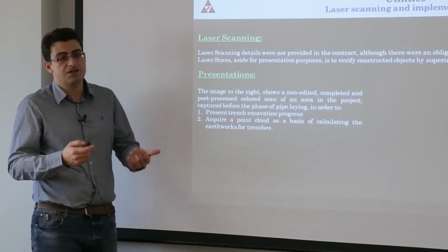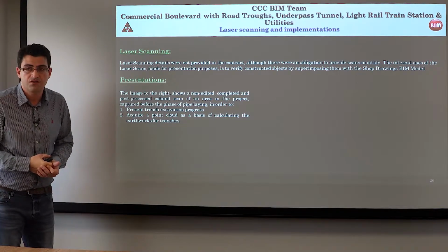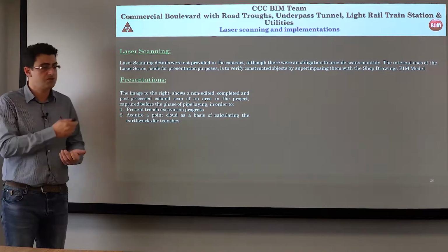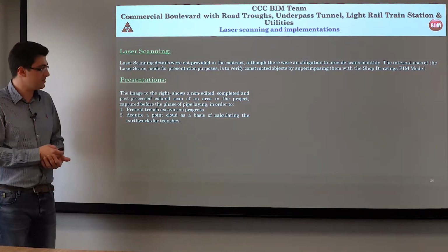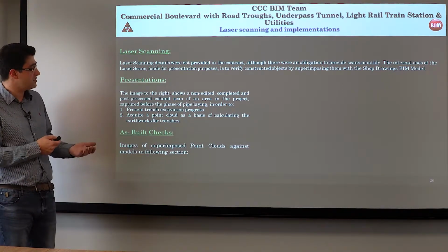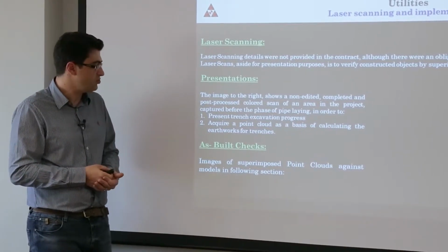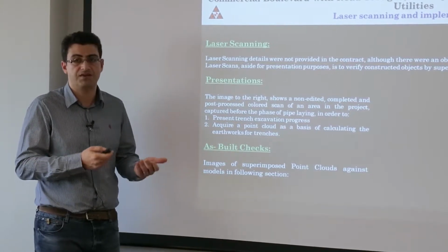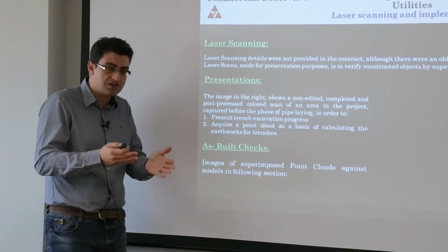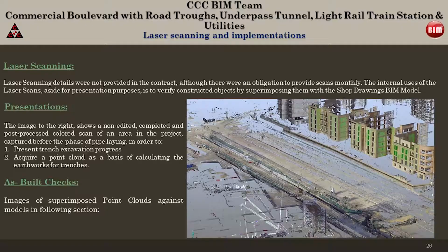And as we found out in our project, we could utilize the point clouds for the excavation, earthworks and backfilling progress, as you saw in the previous presentation part. And as we said, the laser scanned point clouds are utilized primarily to check the as-built, that what we have done on the site is verified in the correct location with the correct dimensions as the elements that we have in our model coming from our shop drawings.